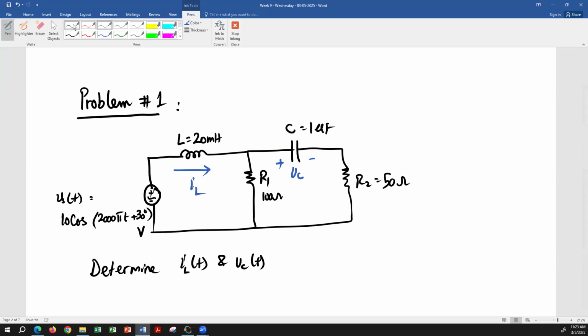And this is not, many students confuse this with the RLC circuit that we did. Remember, if your source is not a DC source, then you're not going to apply the transient analysis of anything. Your source is an AC source, you're going to apply steady state sinusoidal analysis. So you're going to convert everything into complex frequency domain and then solve the circuit.